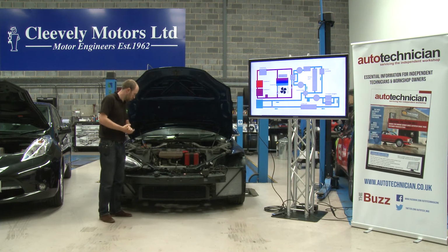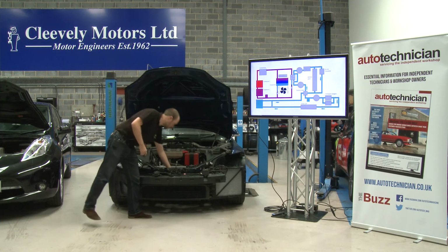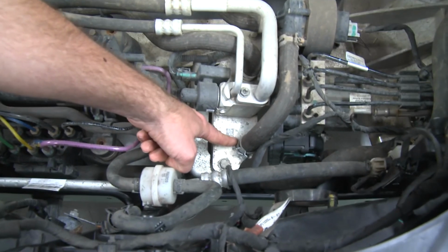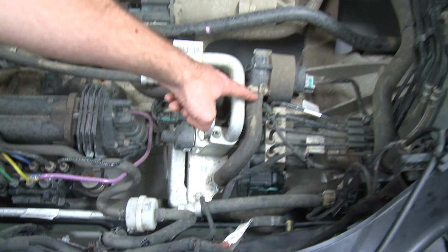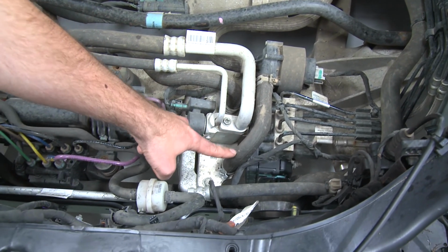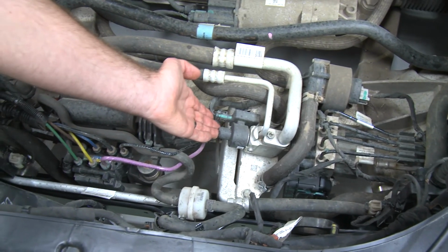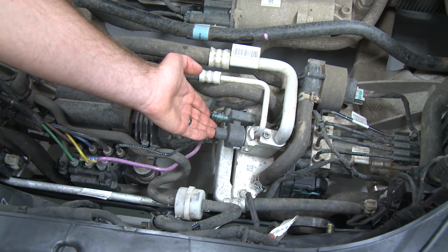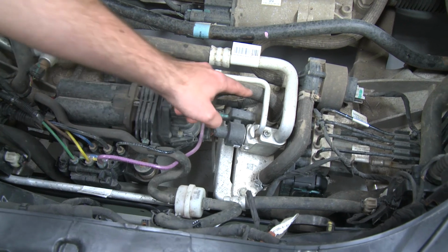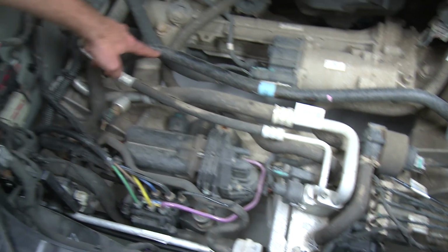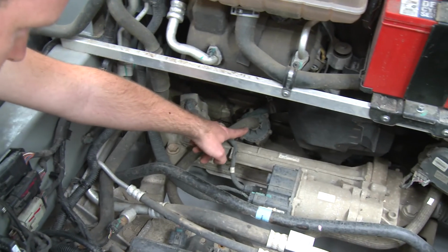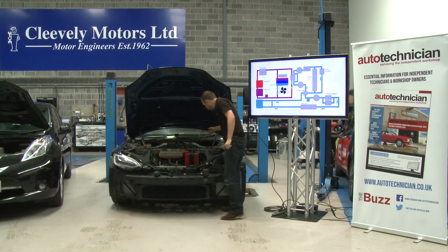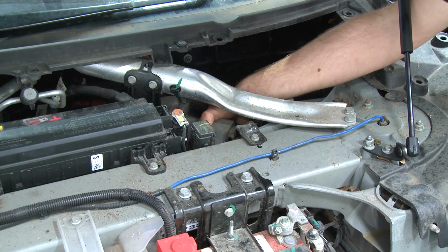And just to show you some of the components, this is our heat exchanger. So you'll see we've got a coolant pipe coming in, so this pump is pumping in this direction. So you'll see coolant coming into here. This little valve allows us to control the refrigerant flowing through it, so we can close it off if we want cabin cooling but not battery cooling. And then this joins up with the rest of the coolant circuit. You can see the second pump in that area, and we can see our third coolant pump in this area here.